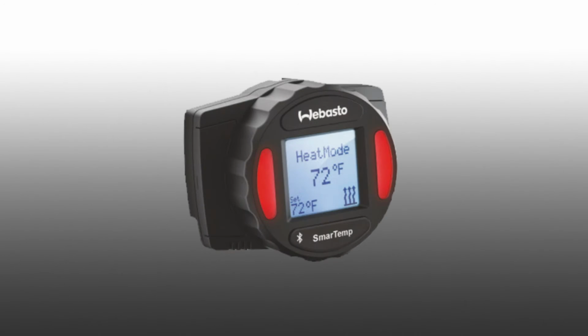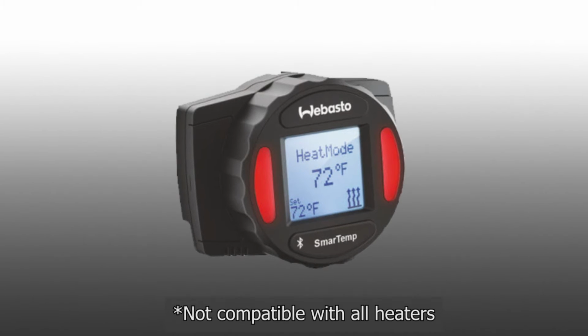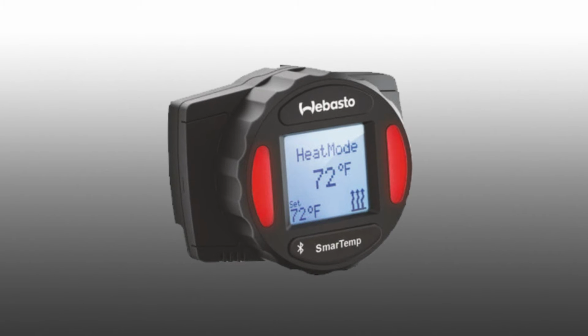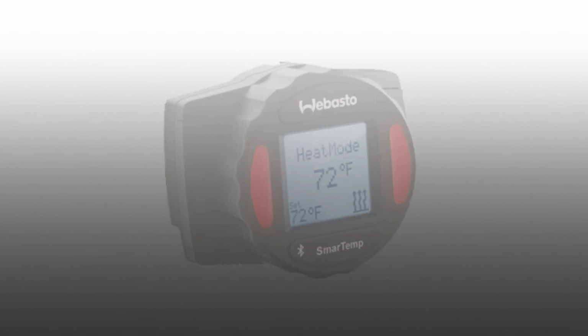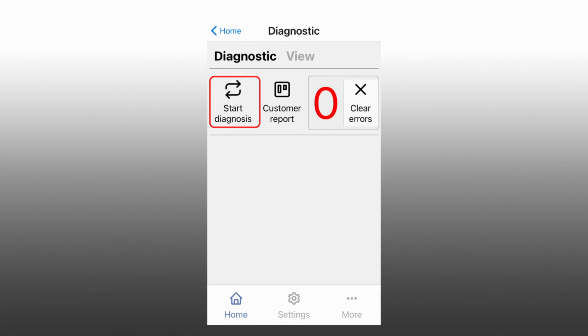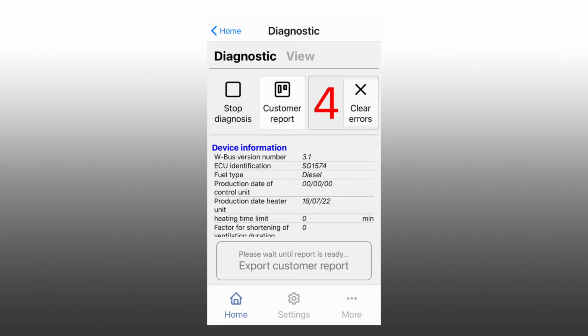If your heater is equipped with the optional SmartTemp 3.0 digital timer with Bluetooth functionality, you can view and even export a customer report right from the accompanying SmartTemp 3.0 mobile app. From the home screen, tap on the diagnostic icon. From the diagnostic screen, tap on Start Diagnosis to start reading the diagnostic information available for that model heater. At this point, tap the Customer Report icon to view the diagnostic report.